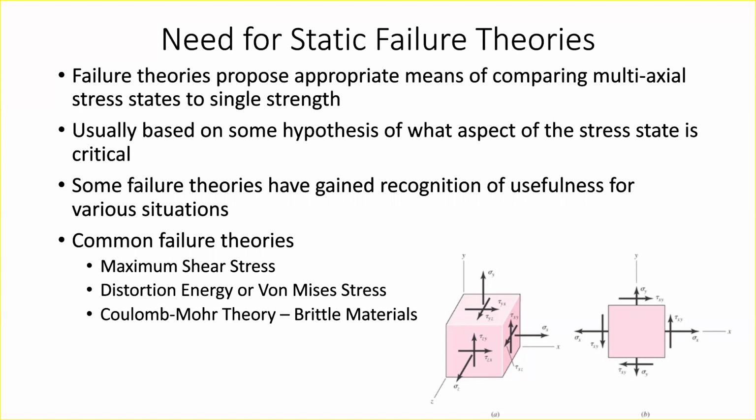You give the FEA your constraints, you give it the geometry of your part, and you give it properties like stiffness, and it's loading the part and assigning a stress to each point within the part, that differential element that we were talking about. So based on that differential element, it then goes to a failure theory to say, does the part actually fail here or not? The super common one that you'll see used in FEA, I'm actually forgetting. I thought it was Coulomb-Mohr, but I think I have it in a later slide. But yeah, it's just relying on some failure theory to say if the part is failing or not.